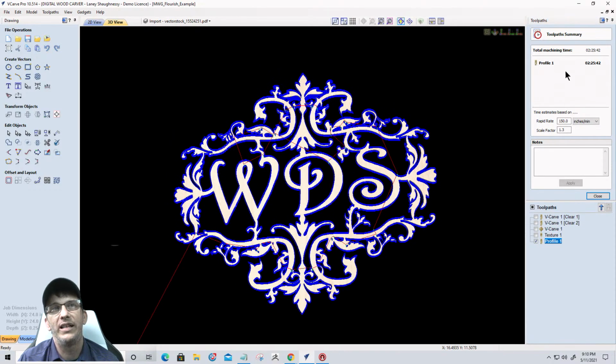Now that's running at my speeds and feeds. I'm running that bit at 45 inches a minute for the feed rate, 15 for the plunge. You can go faster, right? Do whatever you want, but it's my 1/16 inch end mill. I'm very careful with that $60 little 1/16 inch end mill, so I'm running at about 45 inches a minute, spinning at about 22,500 RPMs, and I'm plunging about 15 inches a minute on that. So that would be that.